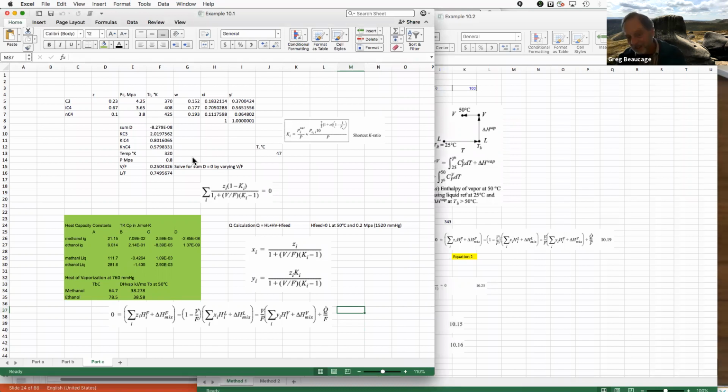The quiz will be like this, like this whole thing that I did as far as examples. The rest of the chapter we'll use later on, more or less. But basically, what you have to get is how to do a bubble point, how to do a dew point, and how to do a flash, an adiabatic flash and an isothermal flash. Get the heat from the isothermal, and the heat is zero for the adiabatic, so solve for the temperature in the adiabatic. That's the most important part of the chapter. There's a lot of other parts to the chapter, so it's a long chapter, but this is the part that'll be on the quiz.